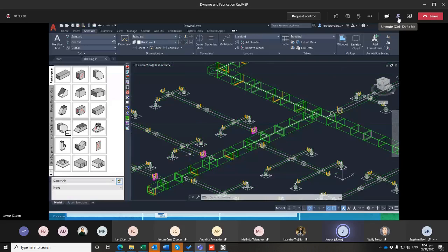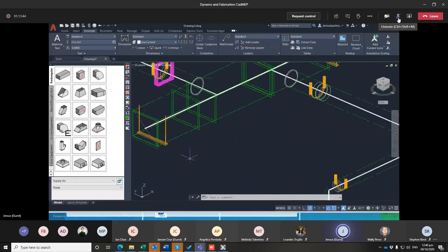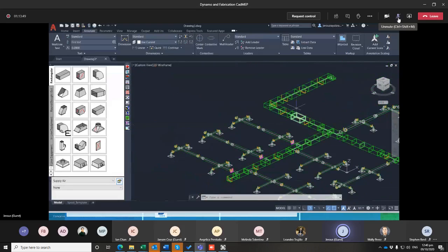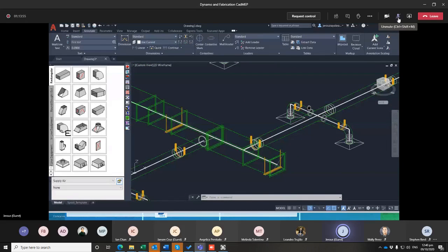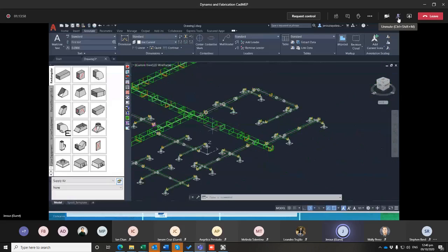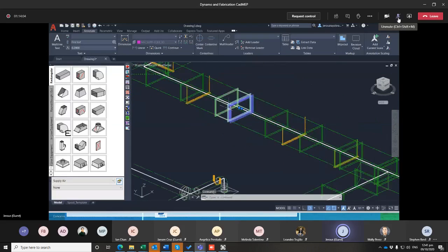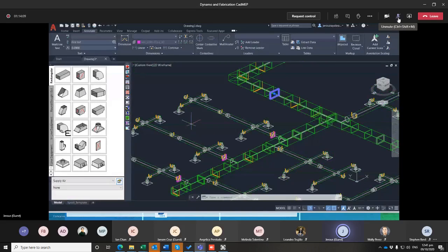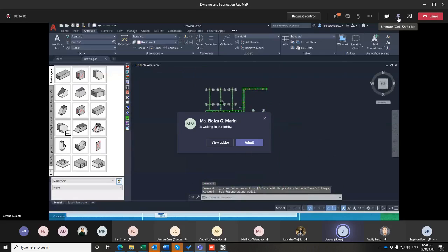So that's why it has segmentized into this. What's good about this is you don't have to put the hangers directly or manually, because those hangers are now in the CAD MEP model as well. There are now hangers, especially for the round ductwork. And most importantly, the fire dampers are now also replaced by fabrication parts. So that's why you want to use CAD MEP for your fabrication parts and not just Revit.